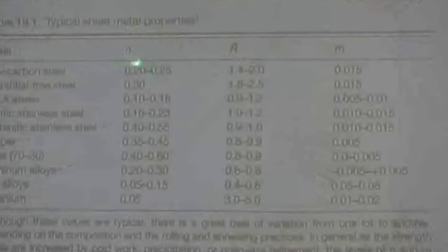So we've been talking about sheet metal properties, and I put this up. This is in Hosford's book, chapter 19, titled Sheet Metal Properties, and he gives you N values, R values, and M values. I've told you N is just the work hardening, power law hardening, so stress is proportional to strain raised to the N power. N's the exponent.